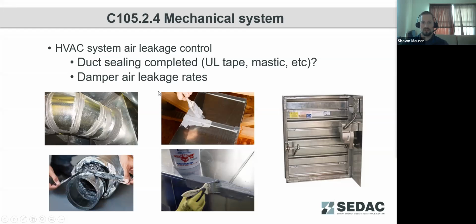For ductwork designed for greater than 3 inches of water column air pressure, static pressure in the system, those do need to be pressure tested per the SMACNA manuals. There are prescriptive duct leakage requirements for high pressure duct systems, which is typically going to apply to ductwork that's right against the air handler, as you can have pressures exceeding 3 inches at ductwork immediately after the fan system.